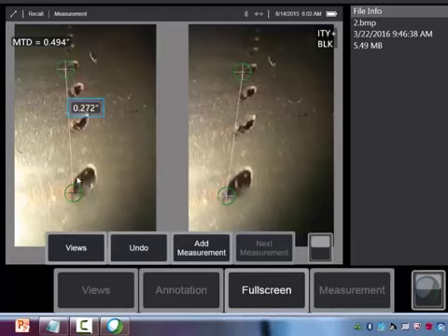Another very common mistake that's made is performing small depth measurements from too far away. Now, why is this such a problem? We talked earlier about how stereo measurement uses this point matching process to identify common surface points in the left and right images, and then it uses that horizontal spacing to calculate the 3D coordinates. Now, this matching process works pretty darn well, but it isn't perfect.